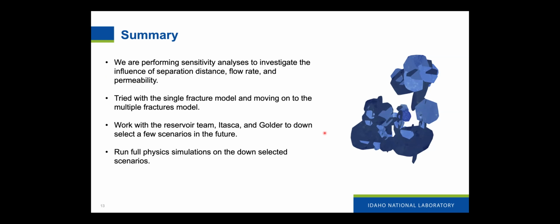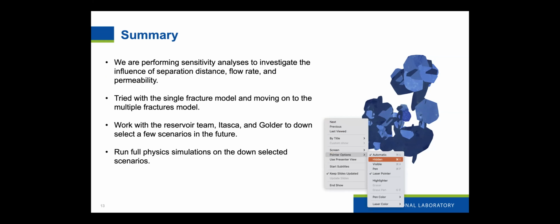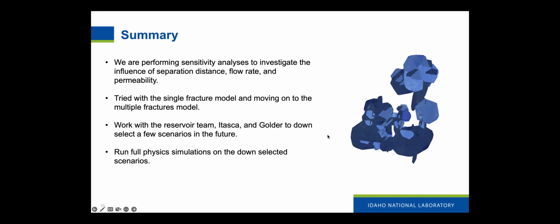Okay, just a few things for commentary before we take questions. The purpose of a lot of these things is that we have to serve multiple purposes with this first production well 16B. So we need to be able to characterize the fractures that we created, which might go to answer some of the questions that we discussed for the stimulation. So we characterize the fracture zones that we created, either single fracture or multiples, and characterize the hydraulic parameters of those. Then we also have to serve the purpose of confirming connection, and then doing some shorter term tests and longer term heat extraction.